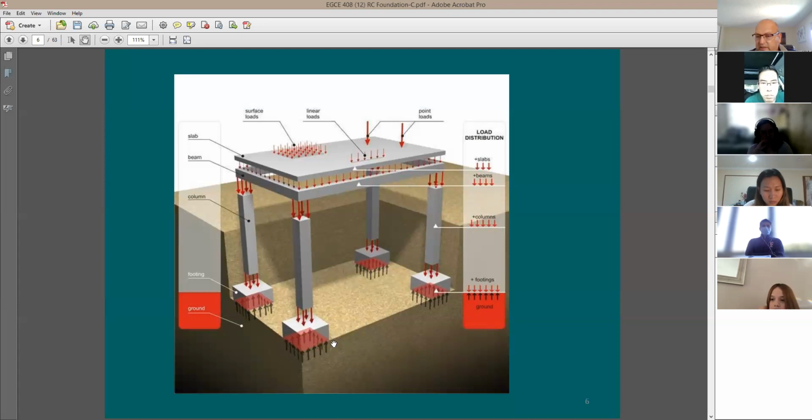In our structural design, we want to be sure that this column is able to support the stresses. And we have done this already by designing the column. Now, after that, we're going to be taking this pressure to the pad, and then from the pad to the soil. Sizing the pad, which means length by width, is to control the soil pressure below this pad. And you want to be sure that it's going to be within the geotechnical report recommendations.